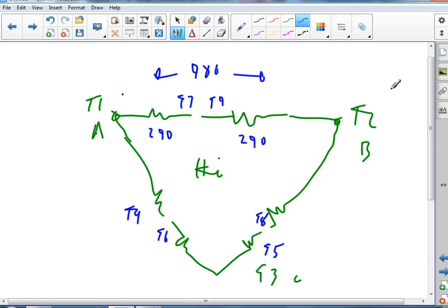So we already did page 1, and now we have to look at page 2. So, how do I get the electricity into the plant? I've got thousands of volts coming into the plant. I'm only using 480 going into the motors. I've got to do something about it. So I've got transformers. On the top part I have transformers, and on the bottom part I have things that are hooked up to the transformers.